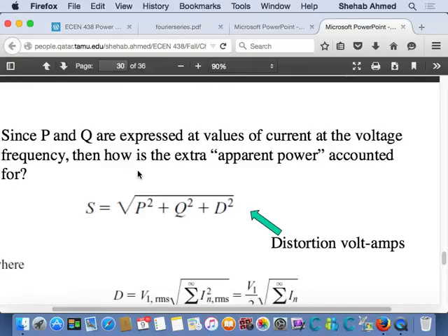RMS voltage and/or current, right? Here in this case, we talked about pure sinusoidal voltage, so it was the current that was causing this trouble, and it's typically the case. So it will definitely have to contribute to the rating of your equipment, right? So this distortion factor that we calculated will increase your apparent power.